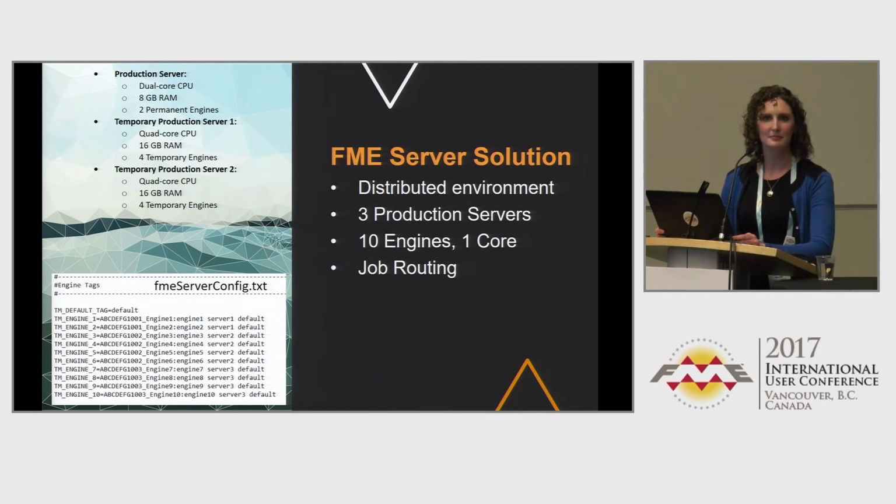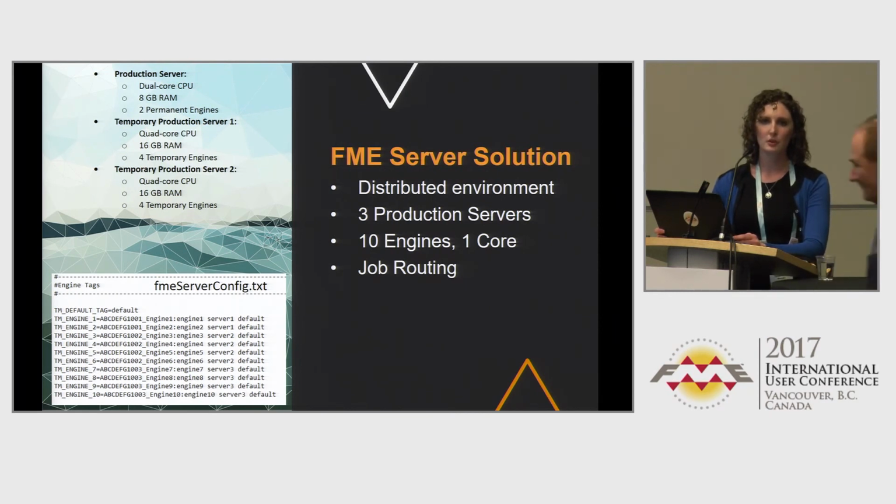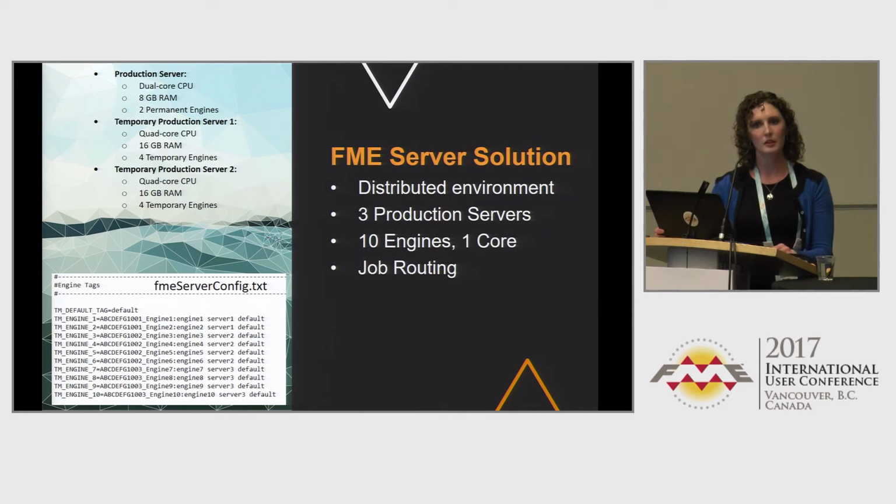Did you have to deal with paper sizes of the original source or the DGN files, and how did you implement it? Kind of. With that custom transformer I created, it determined the orientation of the original file. And that's all I needed to know. They wanted to know if the original file is in portrait, then make it this size. If the original file is landscape, make it this size. So all I had to do was gather the extents for everything in that DGN, and then use those extent values. I just did a simple divide to determine if it was portrait or landscape.